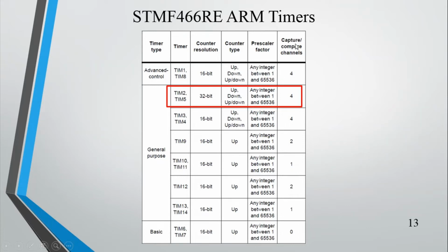So in the case of capture channel you can give input to a particular pin. In the case of compare channel, what do you mean by compare? When a particular time is reached, it is equal to alarm clock. When a particular time is reached, alarm should be set. Here alarm can also be an external event. That means an external event will be generated on a pin.